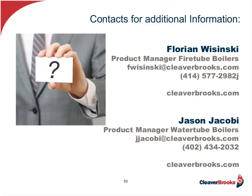With steam systems, you're required to stay with the steel boiler due to corrosion, so you're going to end up with efficiencies in the 80 to 85% range maximum. With a condensing hot water boiler in a heating application, you can get up into the efficiencies in the 90-95% range. So the hot water heating side is being driven strictly from a fuel savings, efficiency, economy perspective is what we see.